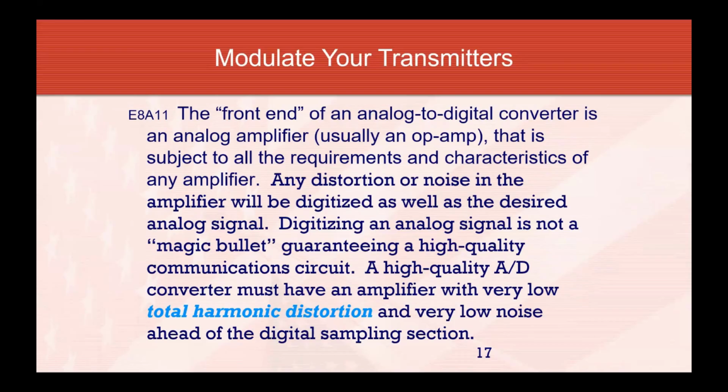At any rate, that amplifier that's going to amplify something going into the ADC, the A to D converter, needs to be a very low noise amplifier, because any noise it generates or any distortion it produces in amplifying that signal will also get digitized. So we want to clean the signal as much as we can coming in before it's digitized, not adding extra garbage to it from a noisy op-amp or some kind of op-amp that would distort our signal more than we wanted it to be.